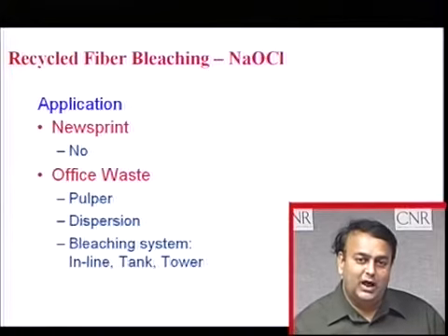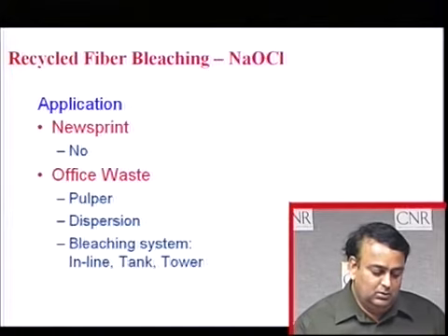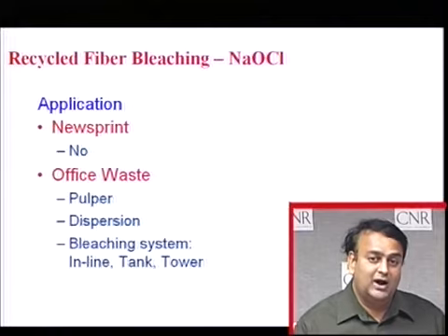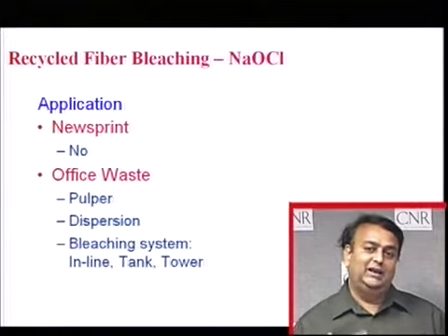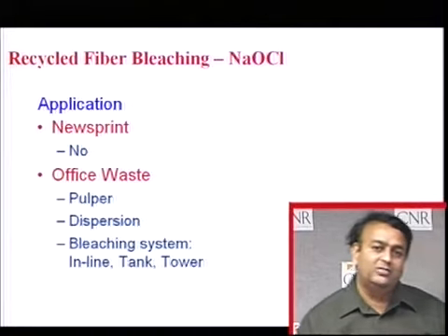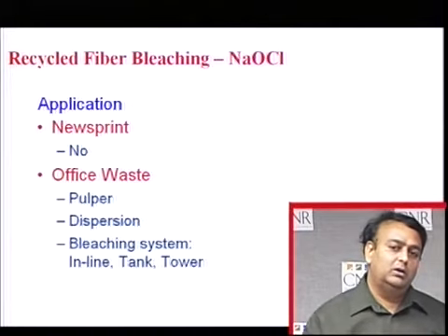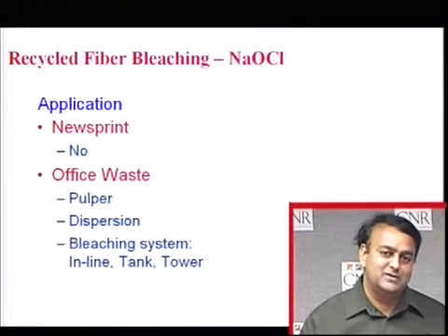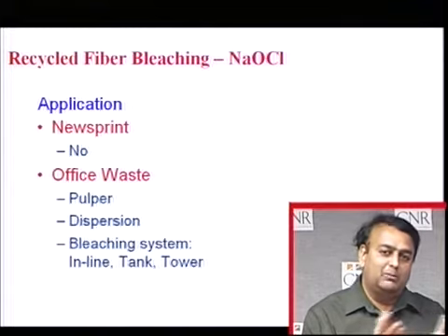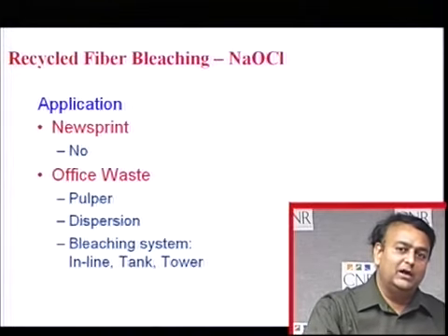Where do you apply hypochlorite? You don't want to apply hypochlorite on high lignin fibers like newsprint. When you have high lignin fibers and you apply oxidative chemicals like chlorine or chlorine dioxide, the kappa number of these fibers is much higher than 100. So the lignin will start bleeding. It will make the fiber yellow. So what you need to do is avoid hypochlorite or chlorinated compound bleaching on newsprint.